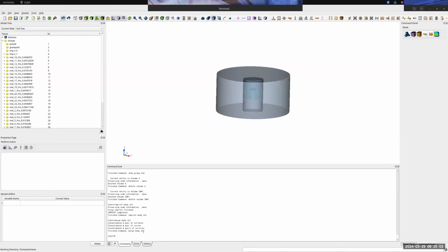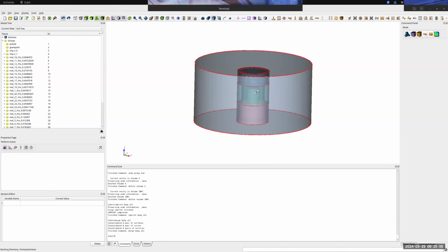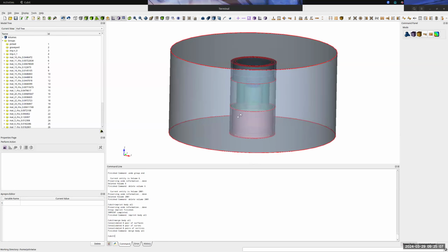And so when I run this, I've already imprinted this model, and we can see that it contains on the interior coincident parts. We see that no surfaces or curves, vertices have been merged. And while that would be concerning in a model that hasn't been imprinted and merged already, in this case, that happened on import. So we don't need to worry about it here. But I always want to note those because those are really critical operations for producing a robust DAGMC.